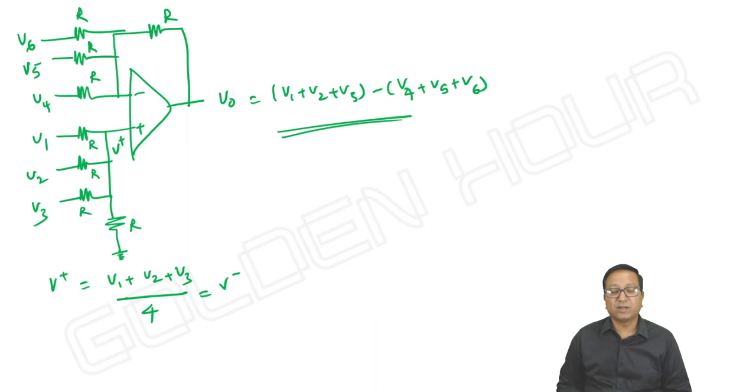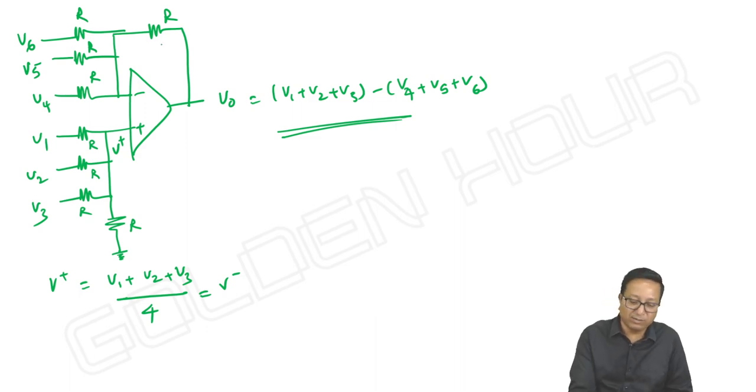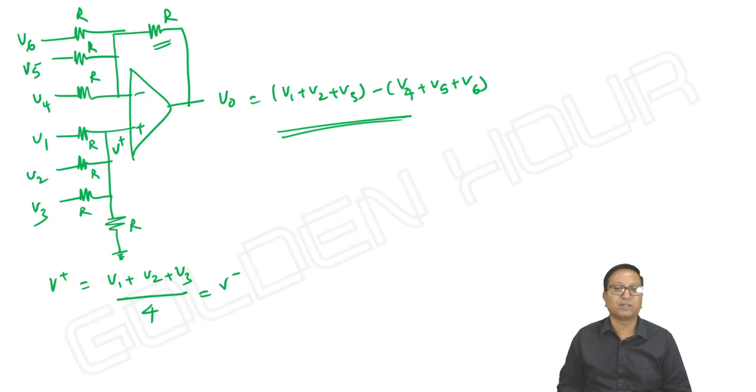It's not like a non-inverting adder. In non-inverting adder, we kept on changing the value of feedback resistor. Here, you need not. That is the difference. If they give different resistor values, the procedure remains the same. Okay.